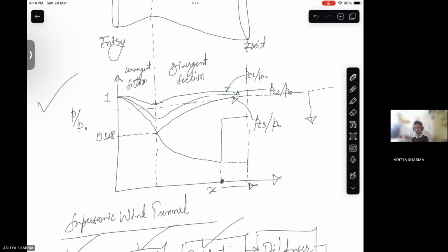And in that case, your static pressure obviously drastically increases, in comparison to the expansion that the flow had experienced, right? Because of the normal shock, there is this drastic increase in the pressure, and the exit pressure reaches this place, which is PE4, right? All right.